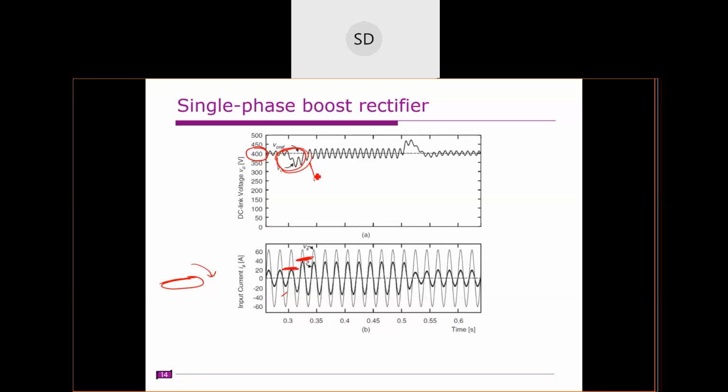But the control is working here, so after some time the control maintains the steady state and increases the voltage. As and when the load is reduced, for example if you remove the load, the speed generally increases. The same thing here: the capacitor voltage slightly increases, and after some time it again reaches the steady state value.